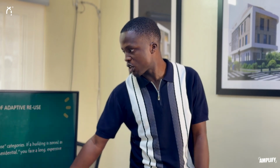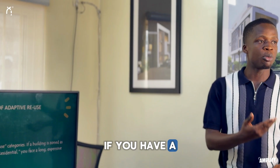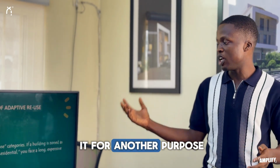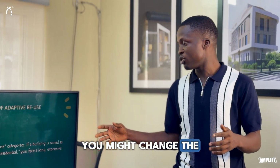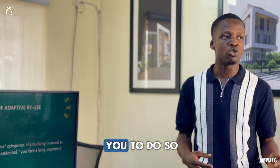And challenges: regulatory and legal barriers, zoning issues. Most cities have strict use categories. If a building is zoned as industrial but you want to make it residential, you may face a long, expensive battle for variance and rezoning. That's if you have a commercial building and you're planning to change it to residential, or trying to use it for another purpose, you might check the zoning laws or the regulatory laws. They might not permit you to do so.